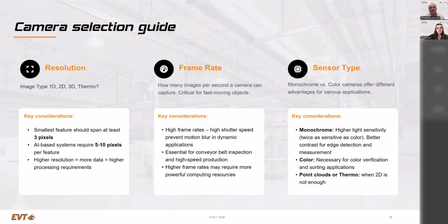Or, of course, you could also use a camera with 60 frames and a high shutter speed. It's exactly the same. If you use a 1/200 second shutter speed, you need the same light. The difference is if you have a 60 frame camera and use a 1/200 shutter speed, the image transfer runs with 1/60 per second. That means you need more time until the image is in your main memory and you can start with the image processing.